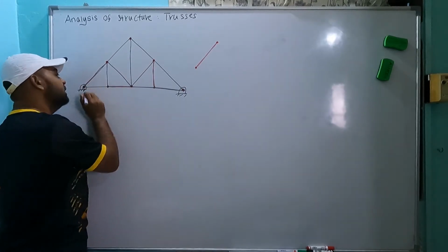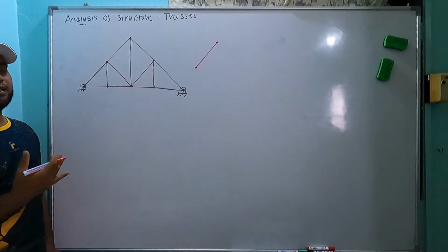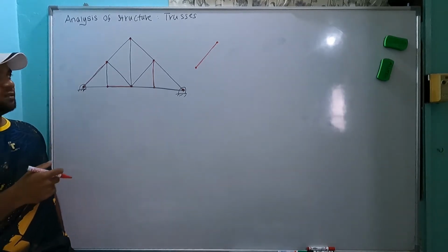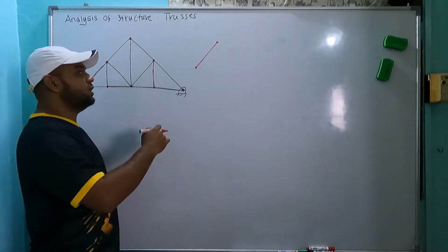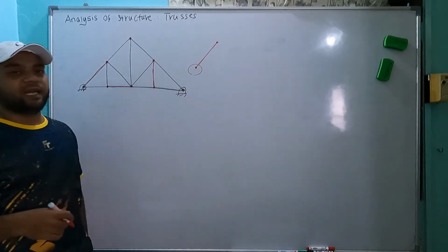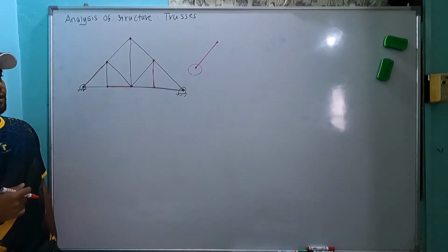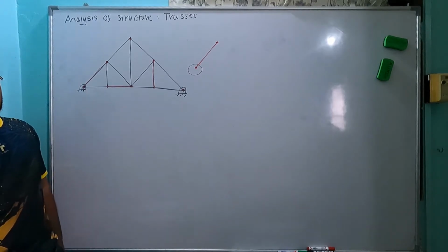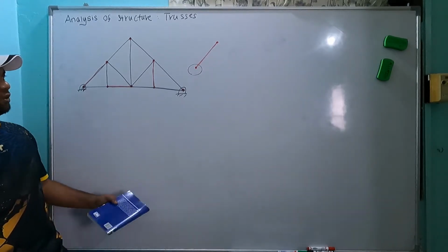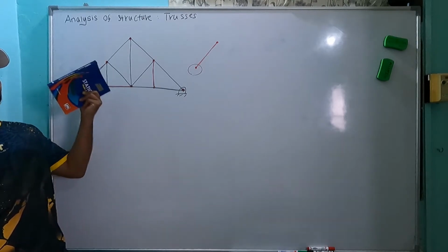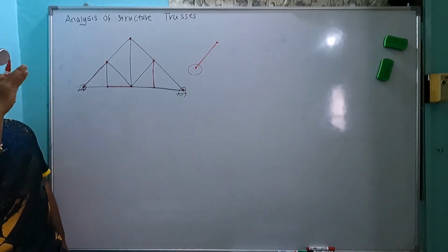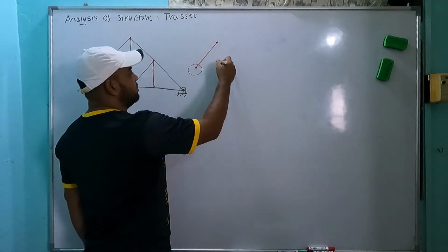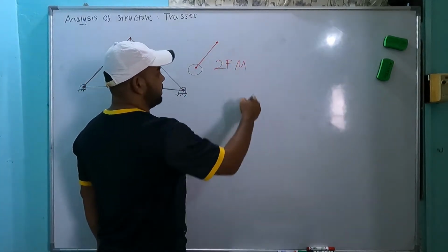We consider the load given, the forces given, will act on that joint through that component, at the end of that joint. Because of that, in most cases we will not consider the mass. Even if we consider the mass, we put the mass at the joint. So all the small components of the truss are considered as two force members.